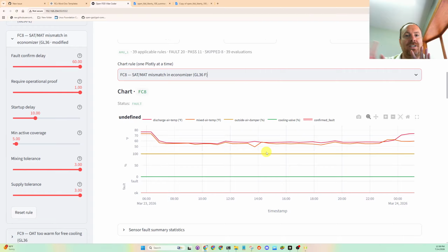They don't economize. They don't ventilate the building at all. Yeah, it just makes no sense because when you would shut the unit down, you'd always close the dampers. So you would expect to see fan status and damper go to 0% all the time. But yeah, there's something off.